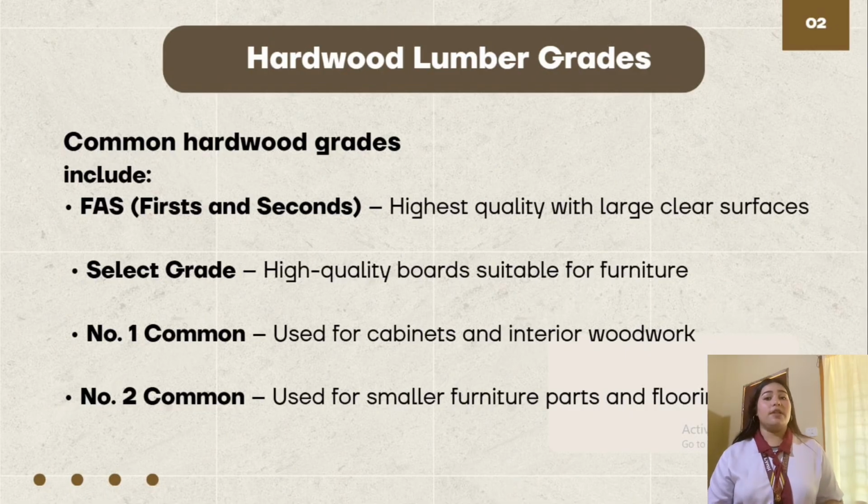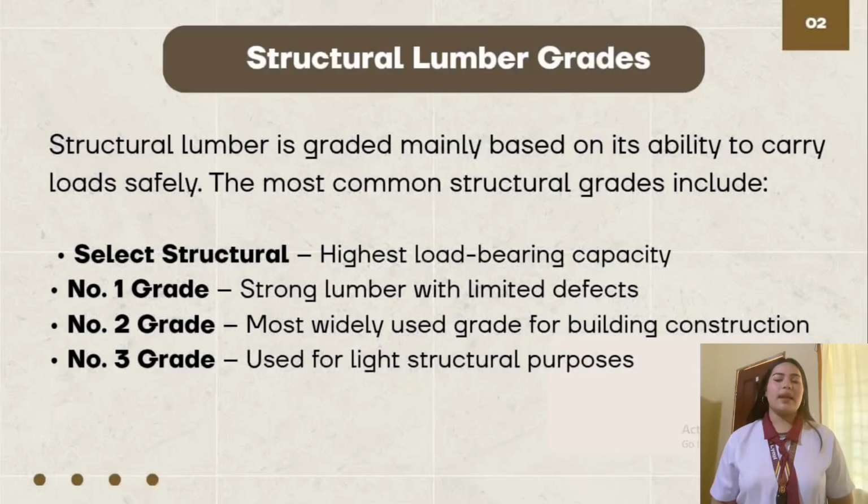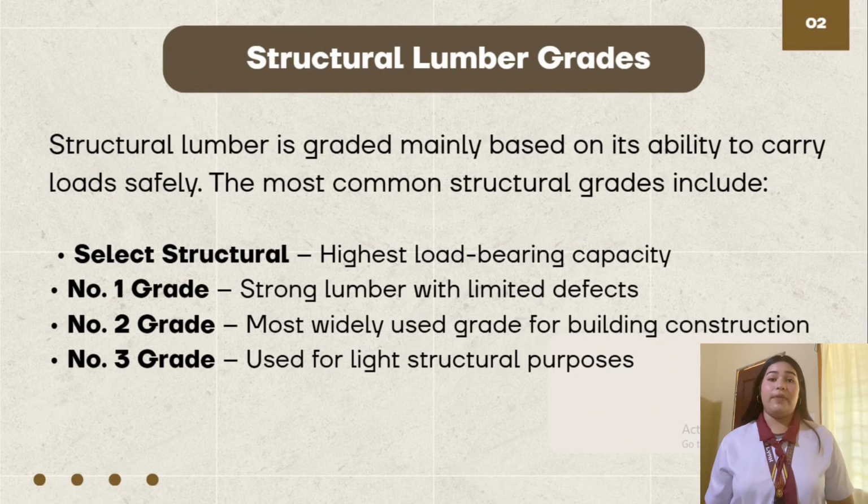Higher grades are for fine furniture, and lower grades are for general interior or structural woodwork. Structural lumber is graded based on its strength and ability to carry load safely. First, we have the select structural. It has the highest load-bearing capacity, used for heavy-duty construction.